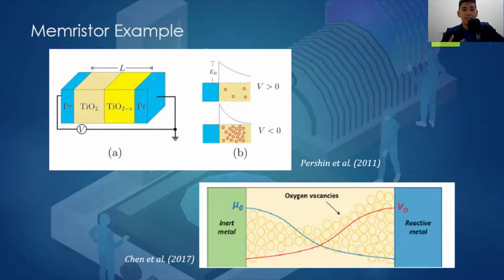Currently we have various emerging memory technologies that are actively being investigated to meet these ideal memory characteristics. And these technologies depend upon the change in resistance. So we have phase change memory or PCM, spin transfer torque magnetoresistive random access memory or STT-MRAM, and resistive random access memory or RRAM.